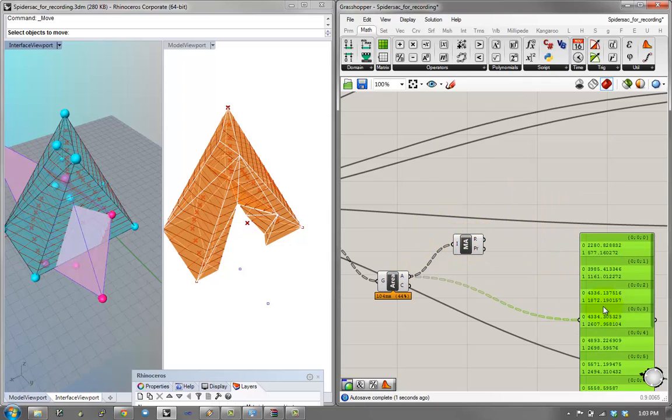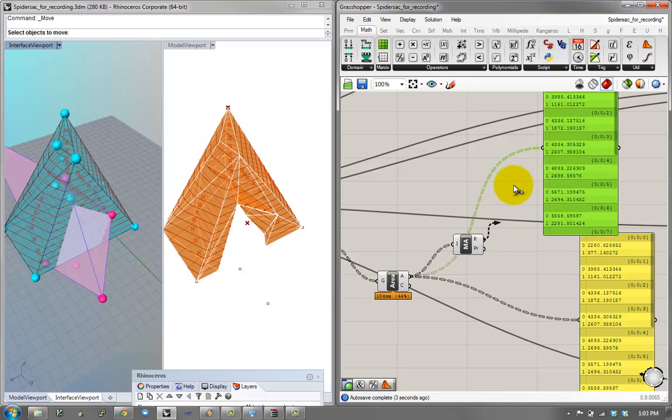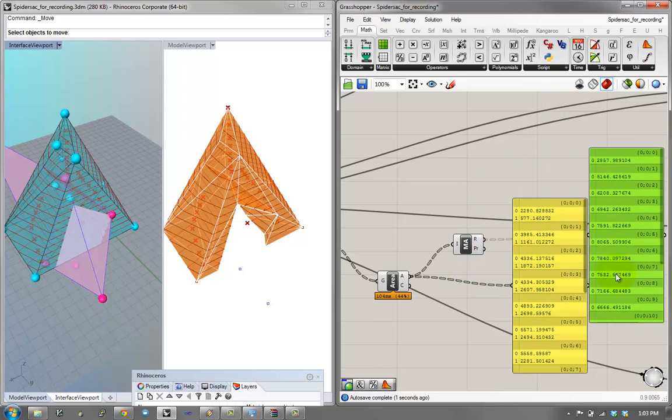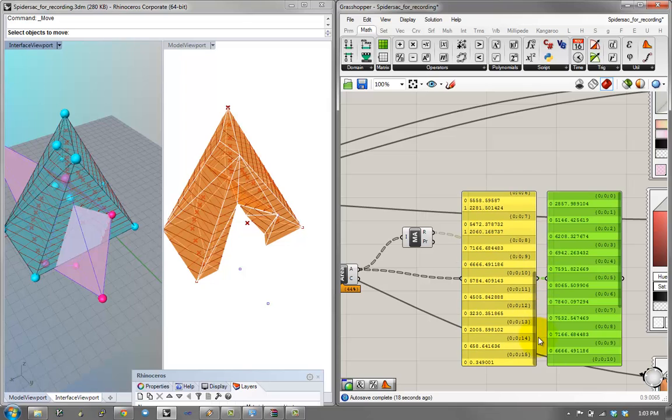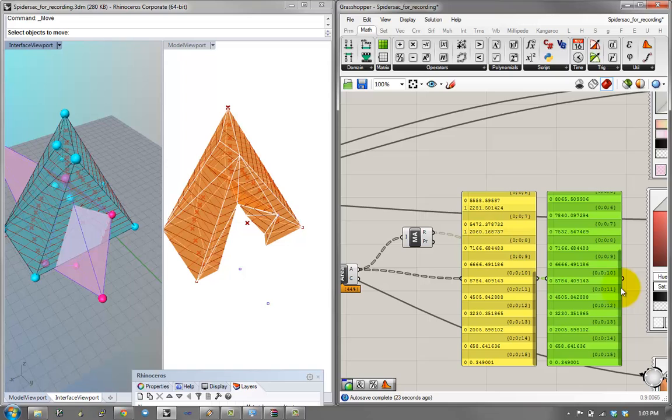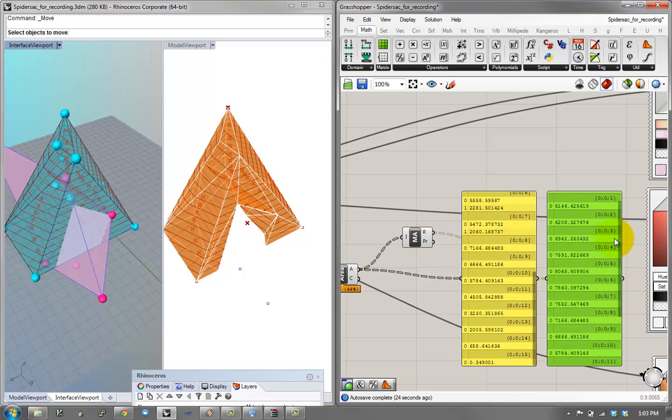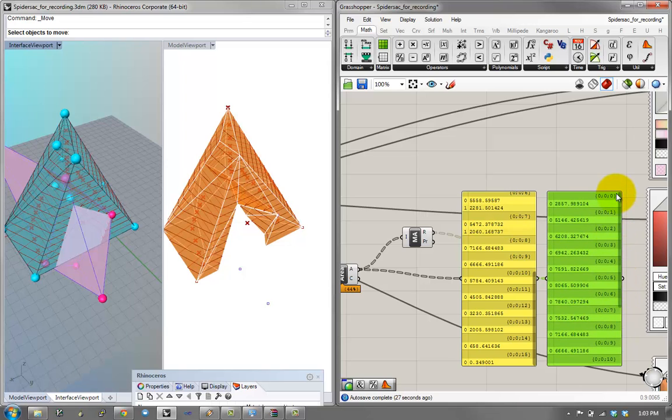And what that does is it adds them together within this branch of a tree. So you can see this gray bar, and it says 2280, 577. That's 2857 added together. Same goes for 3985, 1161. This goes and added together. So this list, added internally together, all of the objects, become this list, which is the total square footage or area of each floor.